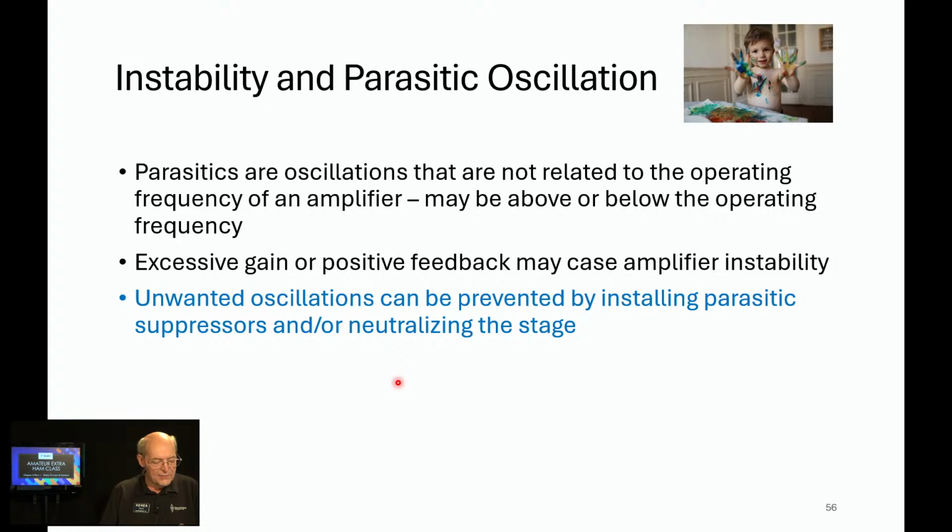And in an RF amplifier, unwanted oscillations can be prevented by installing parasitic suppressors and or neutralizing the stage. And I'll have a picture of that coming up.